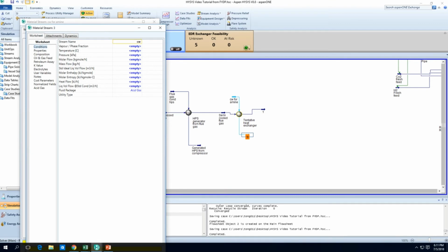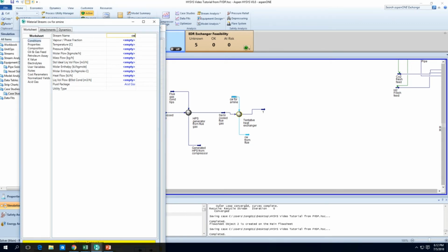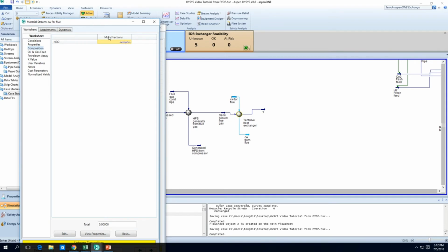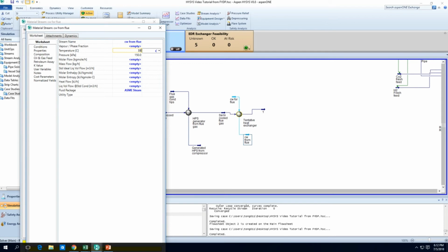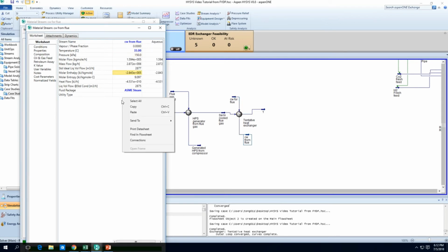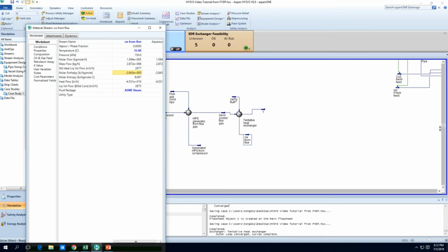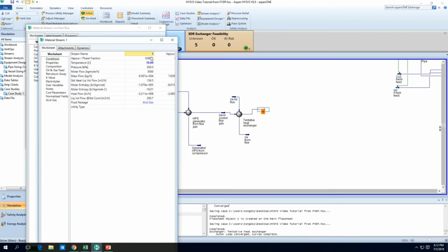So let's put CW from, okay, Flue. Okay, so ASME, again I'll go from 32 to 35. Okay, pressure 250, this is just arbitrary, trying to speed things up. Okay, out will be 35. Okay, there you go. Just a tentative heat exchanger. We might want to optimize or do something about it later, but this is cooled flue gas.